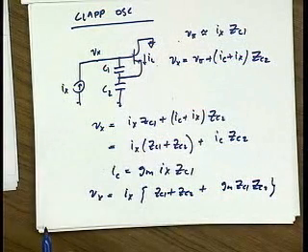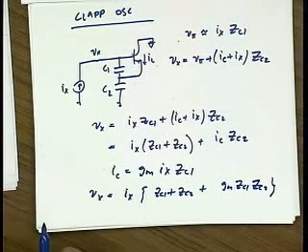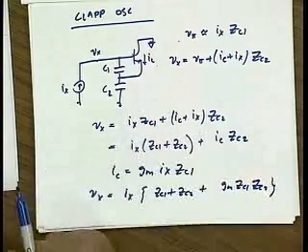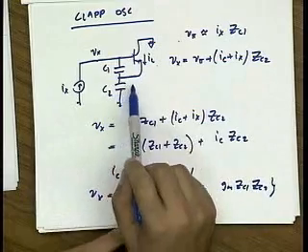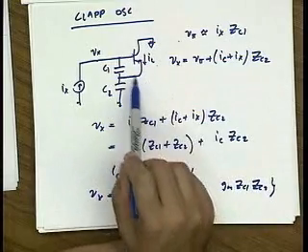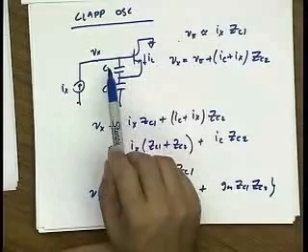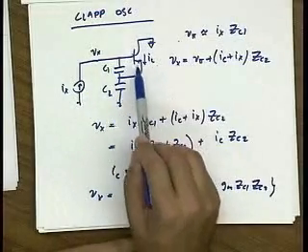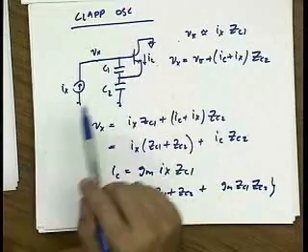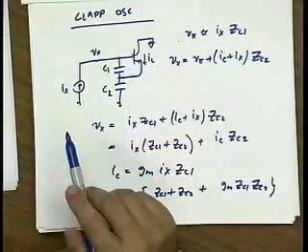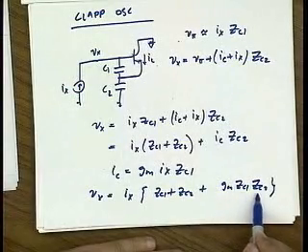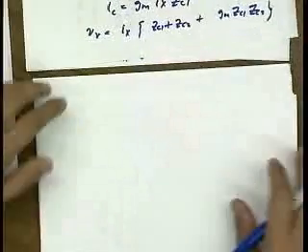Okay. Now if you go back to your analysis of LNAs, you might find this, that we didn't even have to do this, because remember, we found that if you put a degeneration inductance, the input resistance would have a real part. If I degenerate with a capacitance, right, I can absorb C1 into C pi, and then C2 just looks like capacitive degeneration. That should produce a negative input resistance. And you can see here, when I multiply 1 over j omega C1 and 1 over j omega C2, I get a negative real part.